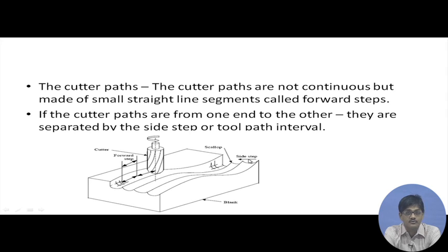Side step or tool path interval: a side step is taken and it resumes its journey along another path to the other side of the workpiece, and these upraised portions are called scallops. So, these upraised portions, just like the forward steps, are creating deviation from the designed surface and